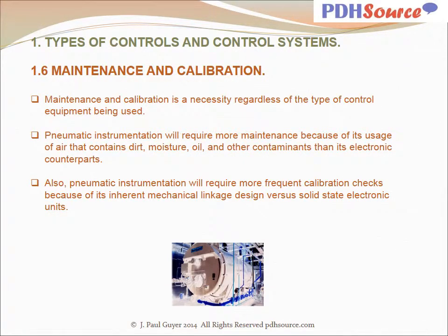Maintenance and calibration is a necessity regardless of the type of control equipment being used. Pneumatic instrumentation will require more maintenance because of its usage of air that contains dirt, moisture, oil, and other contaminants than its electronic counterparts. Also, pneumatic instrumentation will require more frequent calibration checks because of its inherent mechanical linkage design versus solid-state electronic units.